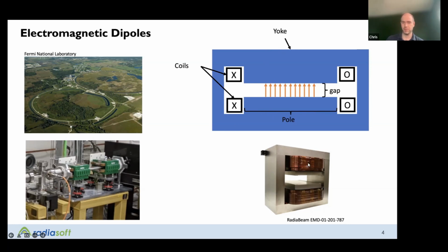If you want to see what that looks like in a full picture, down below here, in the real dipole, you've got the coils actually wrapping around the poles. And so that current is going to excite magnetization in the iron, and you're going to induce a magnetic field across this gap. And so if you have charged particles, say, entering the page, that V cross B force is going to deflect particles to the left or to the right in this uniform magnetic field.